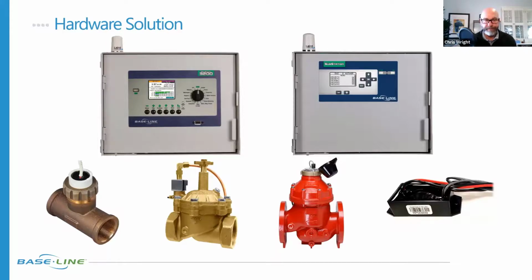Absolutely. Just thinking about what you said about that 36-inch level line, if you're pumping out at 1,500 gallons a minute, you could drop below that in a matter of 3 minutes. You could be well below that 36-inch line if we weren't responding quickly enough. Right. Nice.